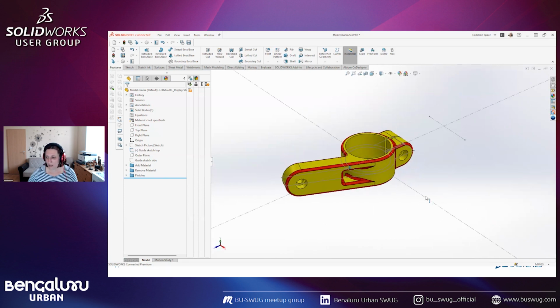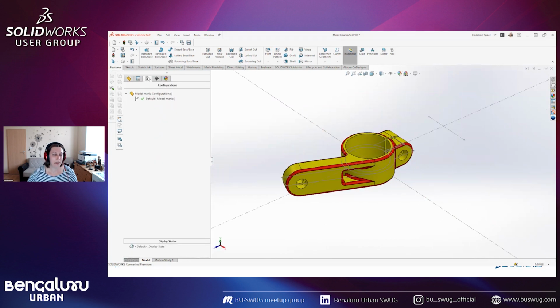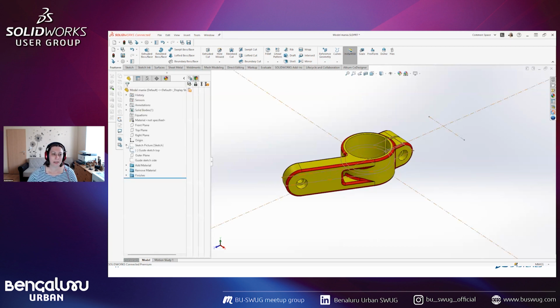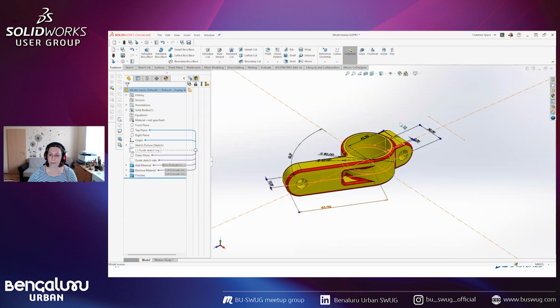The other thing that this gives you is you can add later a design table, add inside the sizes from your base sketch, and you can make different versions of this particular model just in minutes without building every single instance new. That's the part which means that your model should be adaptive, not only to be able to change it without damaging everything, but also to be able to make different versions in one.